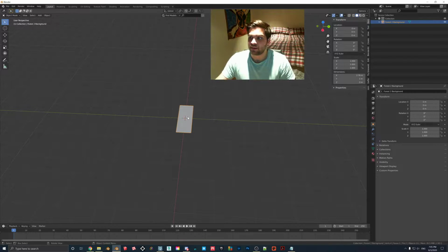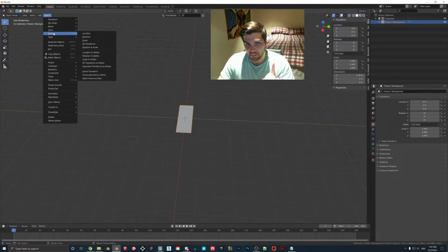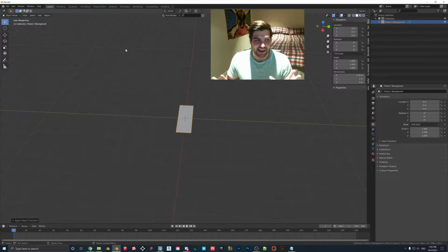We're in the solid mode. So what you want to do is you want to make sure that up in the corner here where it says rotation, you want to make sure all these are 0. If they're not all 0, just manually click on them, hit 0, make sure that they're all like that. And then you have to come up to Object, Apply, Rotation. I know that this might seem like it's weird, and if you start doing this stuff with Blender and you just can't get it, then like I said, just use the ones that I downloaded. It's no big deal. I just figured that I should at least show the people that are kind of familiar with Blender how to do it.